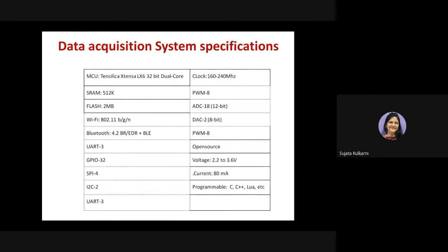So we have to look out for a controller which is supported by freeware, unlimited licensed versions, with no limitations for the students. That's another way of identifying a computational device or the architecture of the CPU. And for the operating speed, we preferred above 100 megahertz computational speed, and preferably at least a 32-bit CPU core, so that high-end mathematical operations can be implemented.